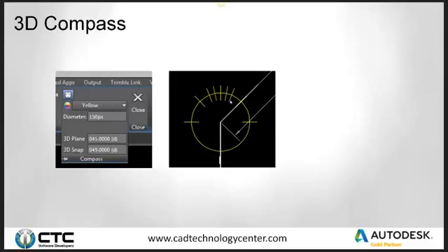I can have a 22.5 degree and then an 11.25. This is really nice because those are the typical degrees for an elbow. So I can just instantly click and say, yep, I want to put it there. And now with my line, it'll only give me 90, 45, 22.5, or 11.25.